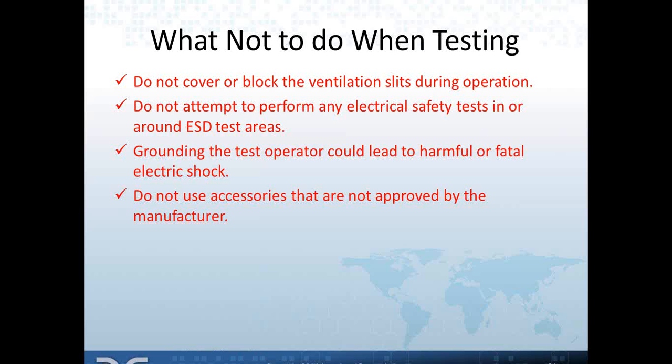Another very important point is not to perform any electrical safety tests in or around ESD areas. Now, ESD and electrical safety testing do not go together. You don't want to ground the test operator, because this can lead to harmful or fatal electric shock.